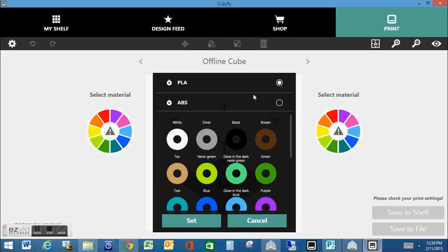If you're not sure, look on the cartridge. The default type that came with your machine is PLA. Now the difference in the 2 plastics, PLA is a vegetable-based plastic, a little bit easier to work with, a little bit lower melting point, not quite as rugged as the other types of plastic, so a little more brittle, but definitely easier to work with. Your ABS plastic is more like the plastic we're used to. It's a little tougher. It's a synthetic-based plastic, and definitely something that holds up a little bit more.